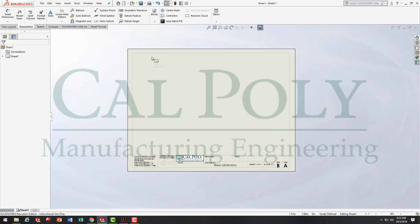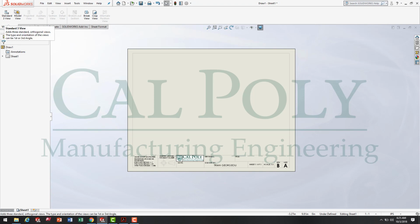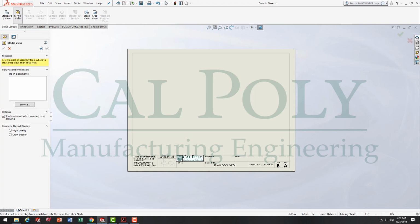Okay, now we're ready to insert drawing views. In order to insert the drawing view, it's under the View Layout. There's two main ways to insert drawing views. There's Standard 3 View and Model View. I'm a bigger fan of Model View because I'm able to put the pictorial view in at the same time, and it seems like an easier method than going back and dragging a projected view off of a standard 3 view in order to create a pictorial view. So, in order to place drawing views onto the 2D drawing sheet, we're going to select Model View.